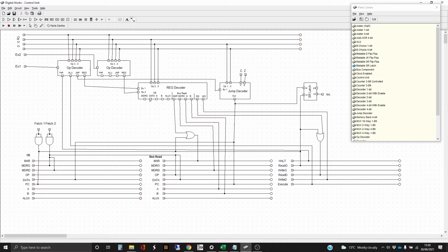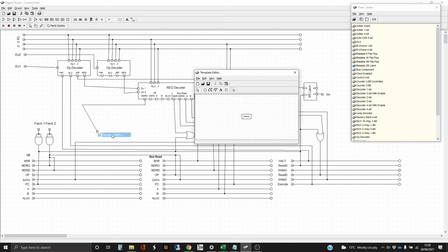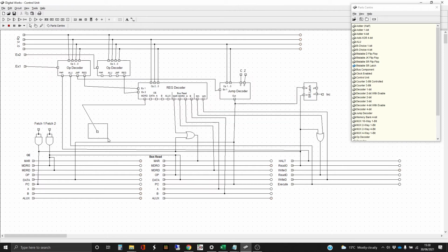So similarly for the output enable, I'm going to start from this end because I'm going to move them around so they kind of stage like that. So again, we're going to see if we're going to need any opcodes. MDRD. I've got a feeling about this, you know. It's MDRD. Yep. All right. So immediately we've got a hit, and we need an opcode. And what is it connected to? MDRD is connected to fetch2. Okay.